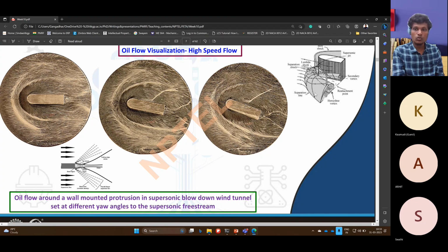And why this horseshoe vortex is forming, we also have to ensure what is the causing mechanism of forming this horseshoe vortex in the supersonic flow. Sometimes it can be a spiral also, not a vortex. We have to differentiate. Many features are there. I don't want to confuse you with spiral and horseshoe vortex, but if it is really a horseshoe vortex, whatever discontinuity is present here, one more discontinuity will be present here also. And why is the discontinuity present? Are you able to understand the idea of separation? What happens at the separation?